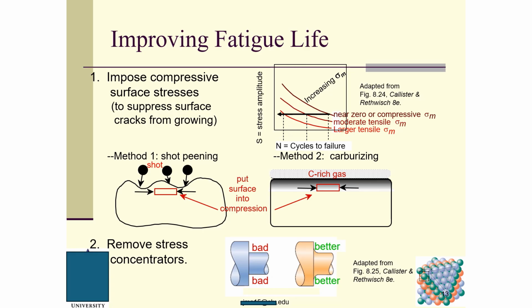Also, one of my research areas is laser shock peening. In laser shock peening, we use a laser beam to induce compressive residual stress in order to improve the fatigue life of the specimen. I want you guys to write down: in addition to shot peening, I also have laser shock peening, using the laser beam to generate compressive residual stress. We call this peening.